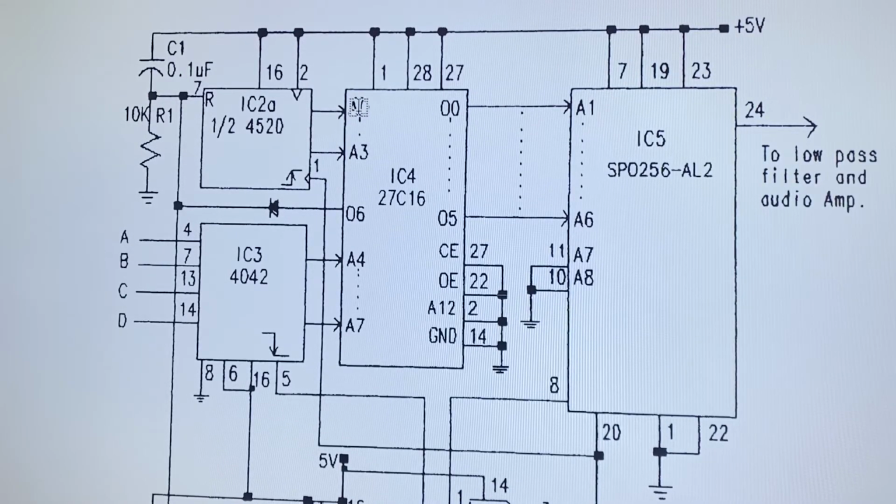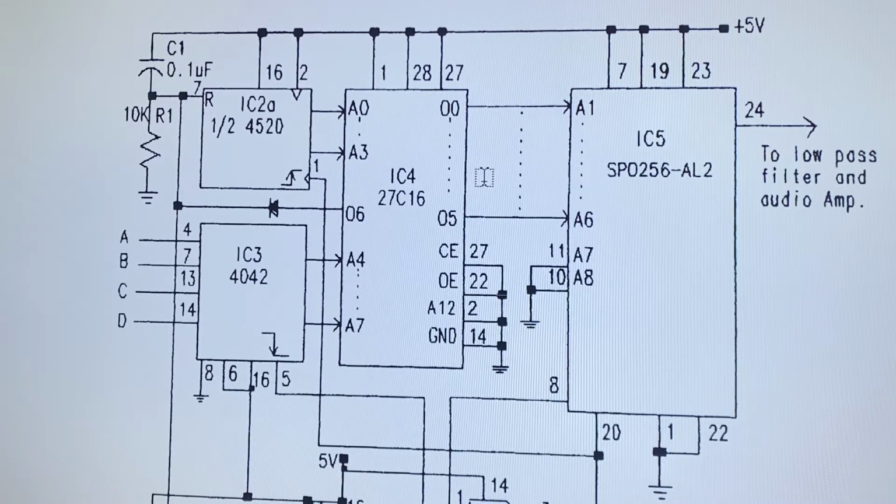Because when you finish the data that you are delivering and you want to stop that, then on output 6 you will write a logic 1, which will immediately reset the counters, and of course the counters will take some nanoseconds, in this case around 300 nanoseconds, to clear, plus the propagation time, the delay that the memory requires to clear the data.